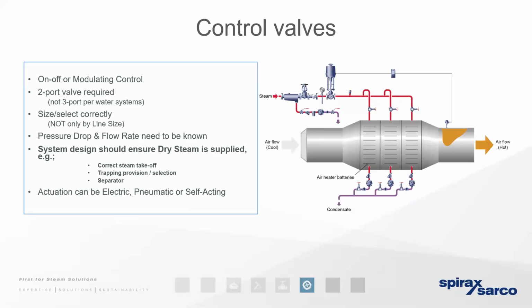And that's principally because, if you'll remember, we want to ensure that the control valve is held in the 60 to 80% open position for the vast majority of its time, where we're not going to get issues caused by erosion or excess wear and tear.